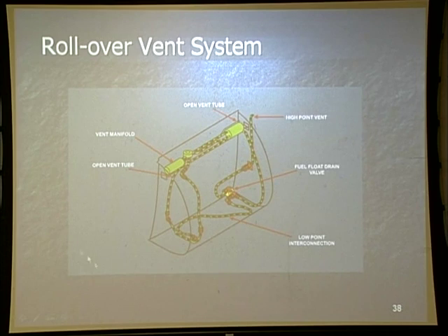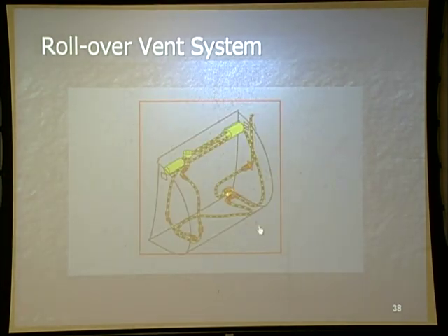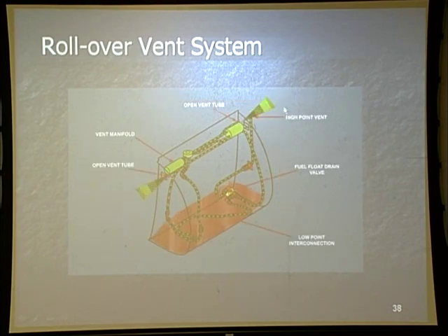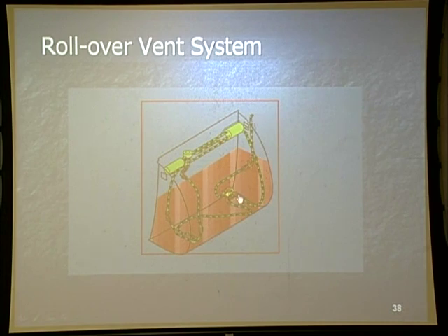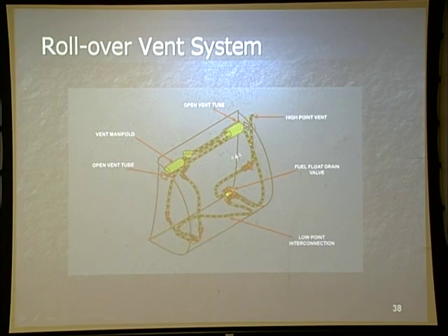But what was happening, and we're actually going to just rewind this so that everybody sees. What's happening is as that fuel's coming out, yes, we're venting the fuel out either via this valve or down at the bottom, because that air is actually going in through those lines and going out through these two vents. One on the top of the aircraft, one on the bottom. Good? As we suck the fuel out, what's going to happen now is that air is being sucked back through, and that air is only coming into the top of the tank.